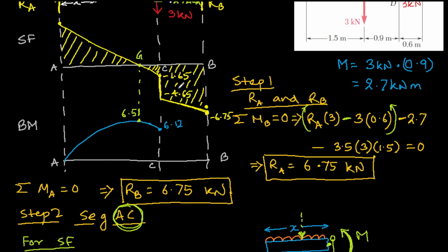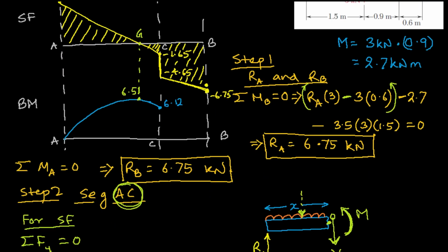And similarly, if you do it for the bending moment, you will get a jump of bending moment here. Okay, in fact this zone is not defined, I shouldn't be drawing this, but I'm just drawing it to make it look good, nothing else. And here there is again a parabola like this, and this value will come out to be 3.42.